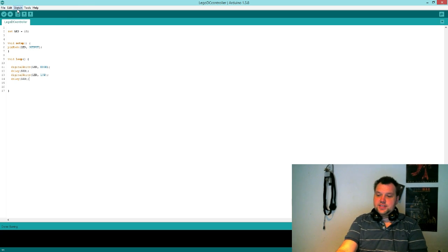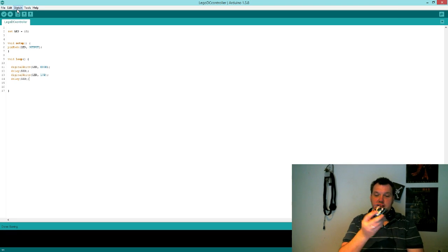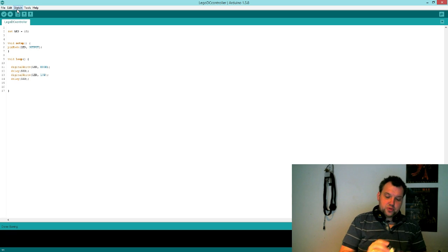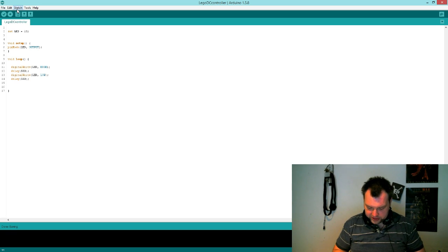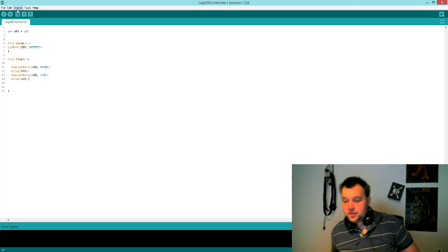And I'm just going to disconnect my motor so I only have the small circuit. I'm going to hook the circuit up to, well, before we do that, let's just fix one thing. One of the legs on the shield was outside the actual board, so it wasn't connecting properly, and we don't want that because that could cause a short circuit.